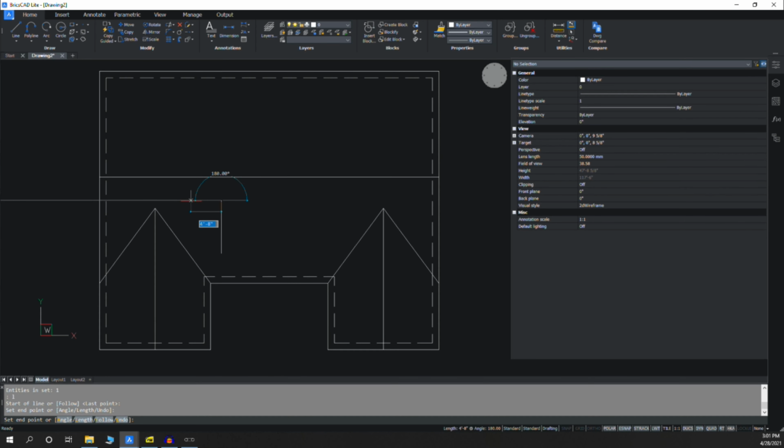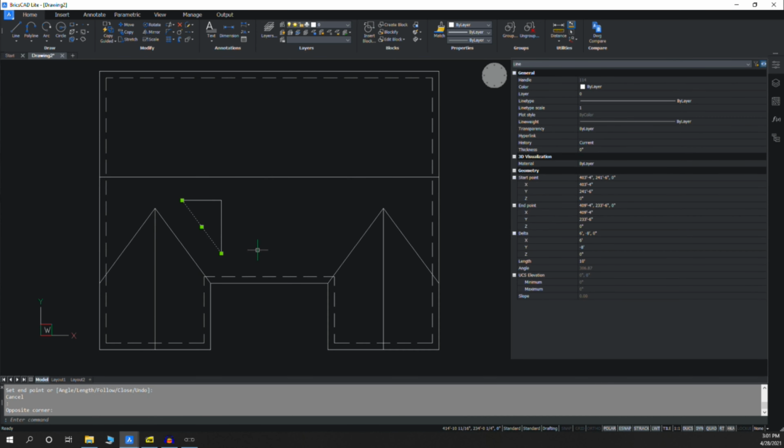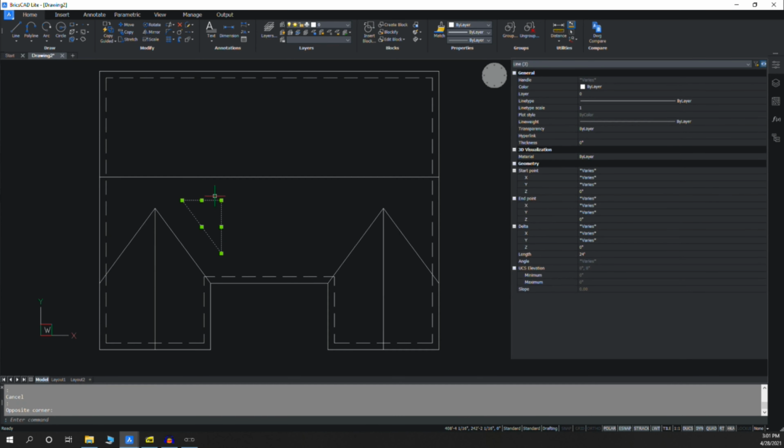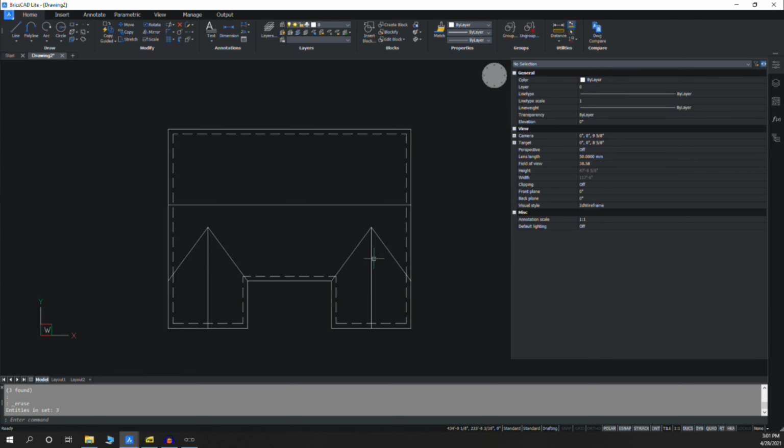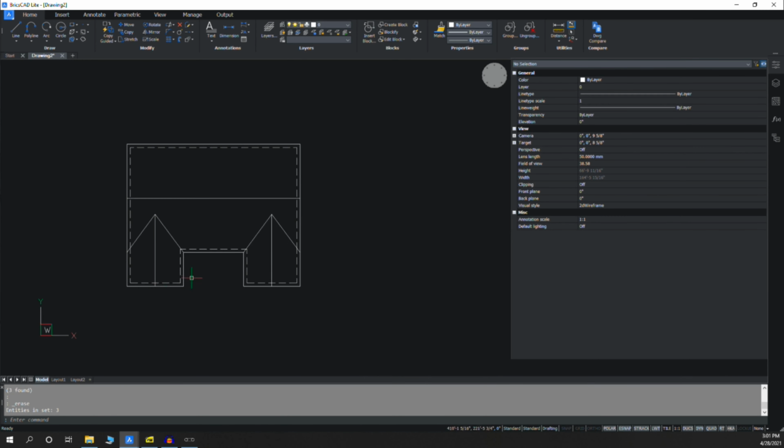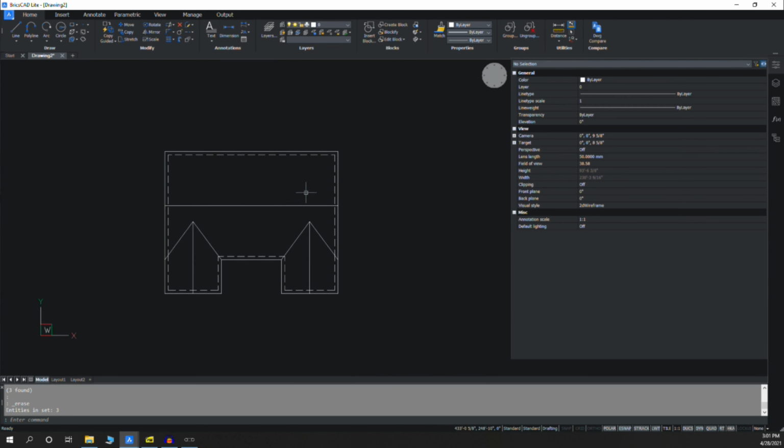In this case, it's an 8/12, so I make it 8 foot. And then you make another line parallel to the ridge line of the roof you're intersecting with and make it the same length as the pitch of that roof, so 6 foot. And then this angle becomes the slope of your valley. So it's complex, but once you remember that, all of a sudden you can do any sort of crazy roof intersections. So this wasn't that bad.